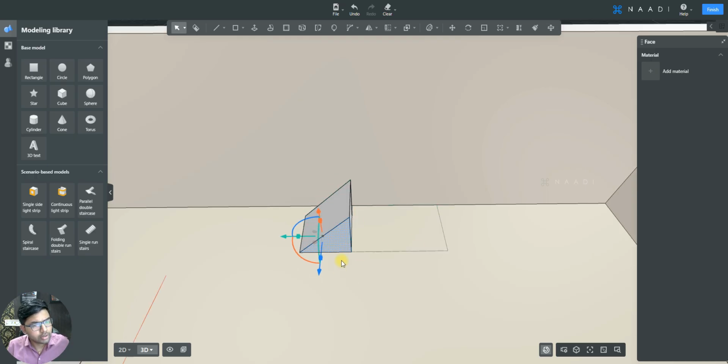But what about the corners? If you notice, if I do that process, your corners won't be articulated, right? It will be like a separated corner. But I don't want that. I want to create a seamless corner, just like how that surface has continuously extruded in that path. In this kind of scenario, your push-pull won't be an apt tool. This is where your sweep tool comes in.